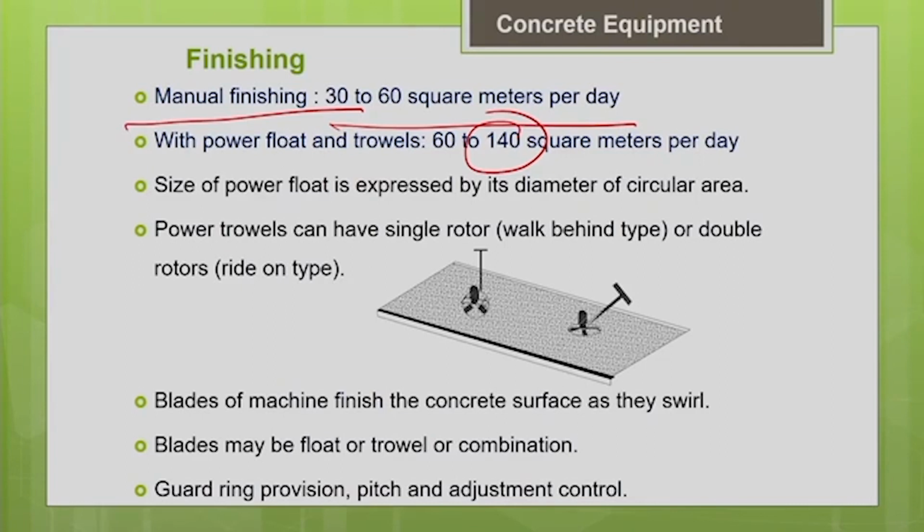So, it all depends upon your project requirements. If it is mentioned in your contract specifications that the variation in the undulation levels accepted is very much less, in that case it is preferable to go for finishing machines like power trowels, so that you can have a perfect leveling and finishing.